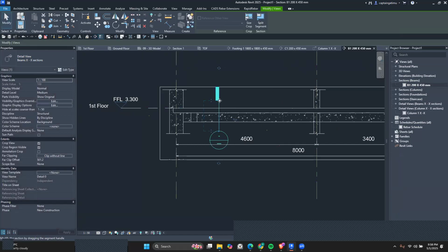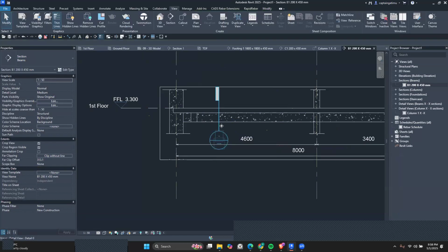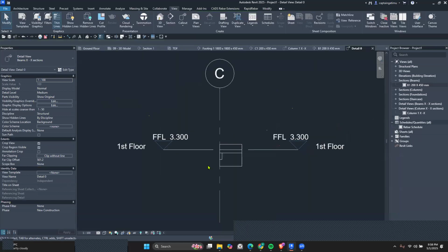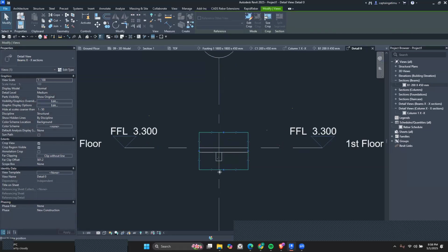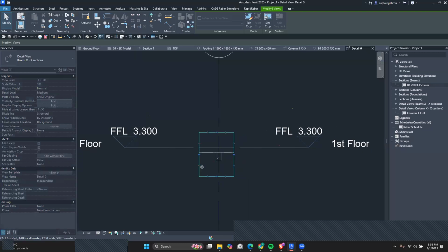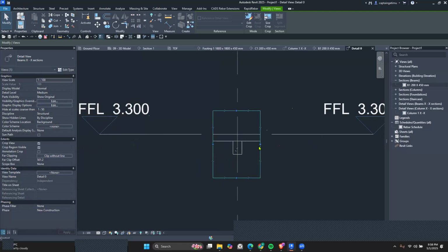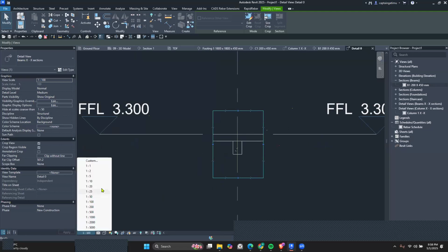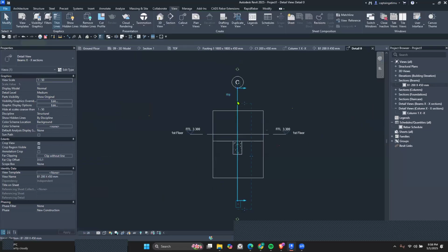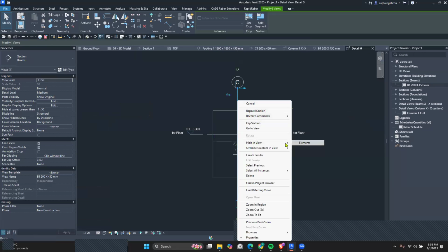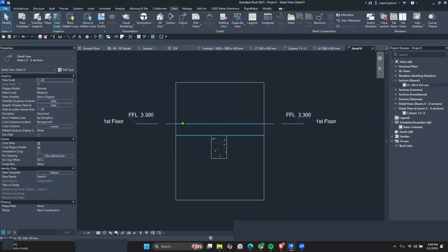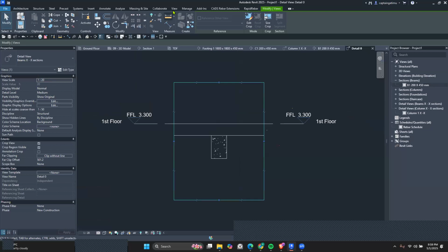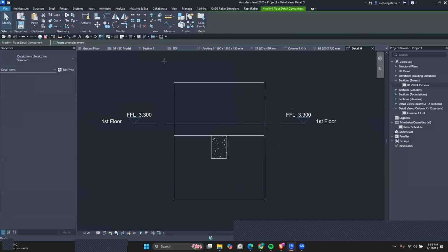And then go to view. I'm not going to go through the step of renaming it, just for time's sake. Then I will select this view, expand it a little bit, and then place it here. All right. So I'm going to change the scale to 1:20, as we saw. Then hide these elements in view: right click, hide in view.